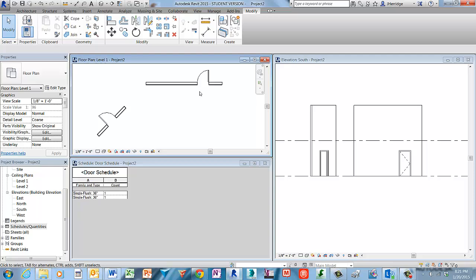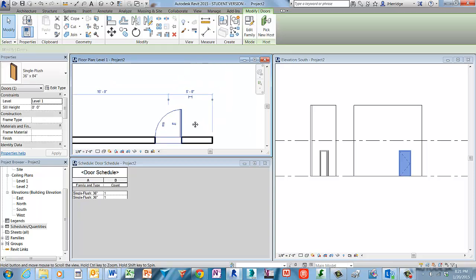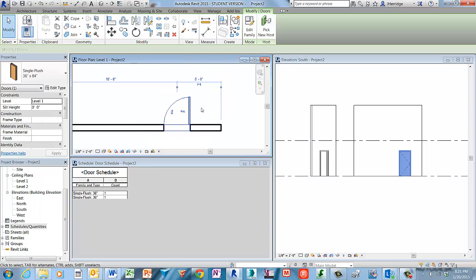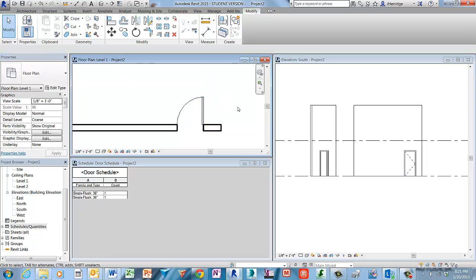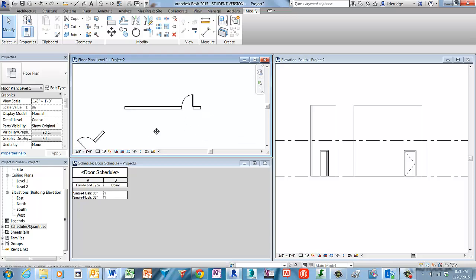All right, to position doors with precision, again, we can use the shape handles for the witness line for the dimension, place it on the edge that you wish to work from, and then again left click to change its value and hit the enter key to accept. So if you want to create an offset for a specific distance from an adjacent wall, that would be the process for doing so.